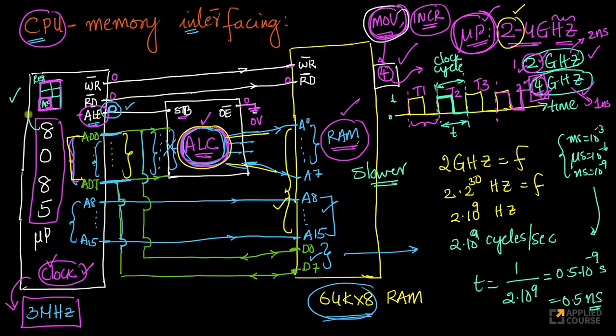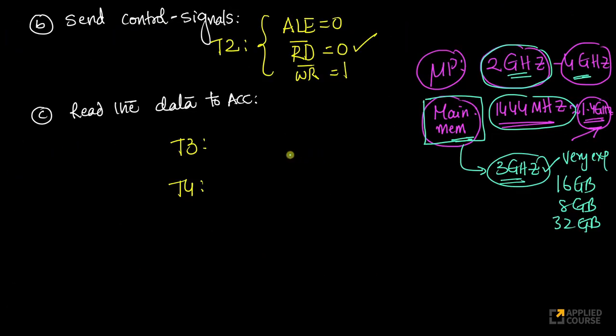That's why accessing data from your registers is faster than accessing data from the RAM. Right? Because registers are operating at the same clock speed as your microprocessor itself. You can actually access registers at the clock speed of the microprocessor, but the RAM itself is slower. So till now we have been saying that accessing data from the RAM is slower than accessing data from the registers. Why is it so? Because RAM's internal clock at which it operates is slower than the clock speed of microprocessors in most real world applications.